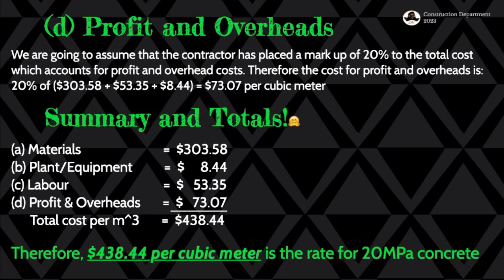We are saying per cubic meter because the 30% was just for us to achieve a cubic meter. It's not just an increment, but it's something so that we can achieve that cubic meter when shrinkage happens. We are not going to be disadvantaged, and then we end up underpricing things. So we don't want to be disadvantaged in the project, so we have to account for that.